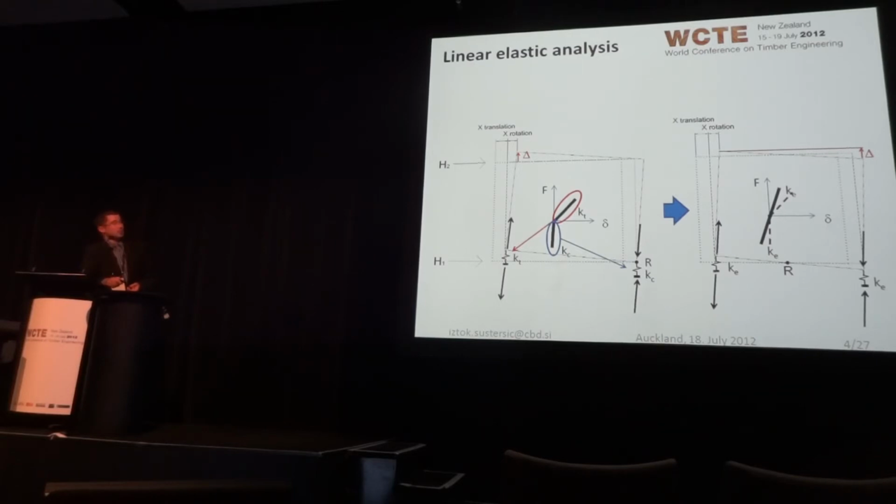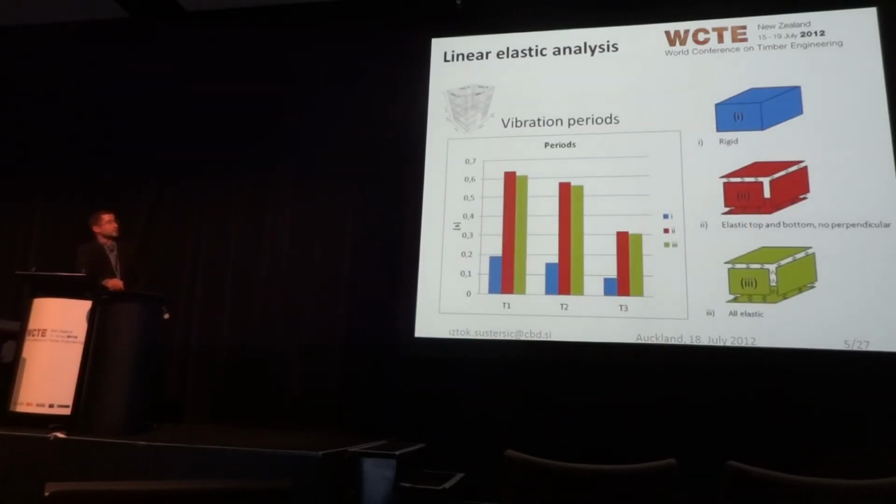But in the meantime, I want to show you what happens if the periods or the stiffness is assessed wrongly. Now, three very simple buildings. The blue one represents a completely stiffly modeled structure, which is something that probably some engineers dealing with concrete will do, because they're used to modeling everything stiff.